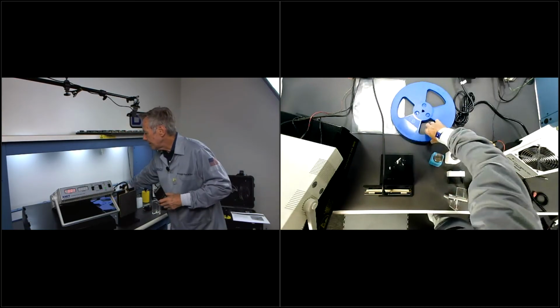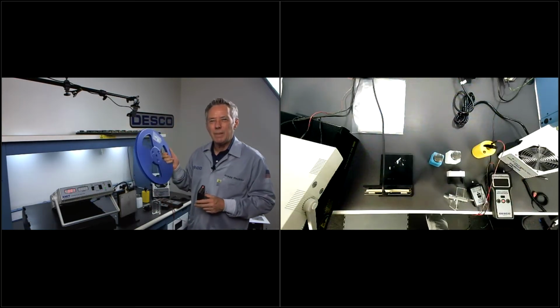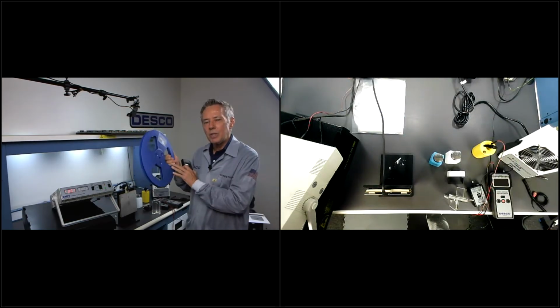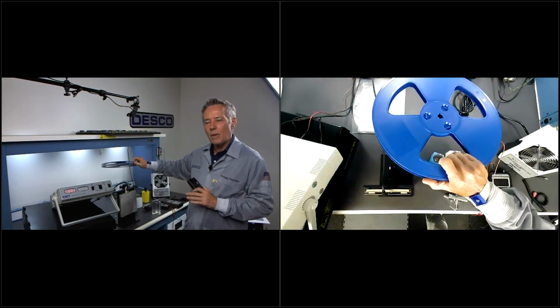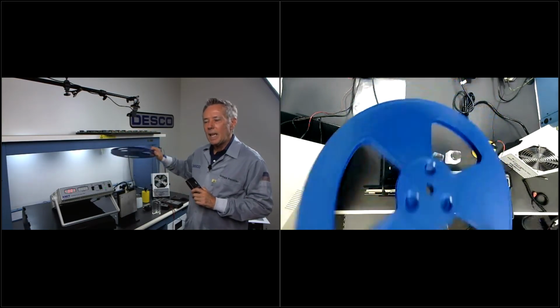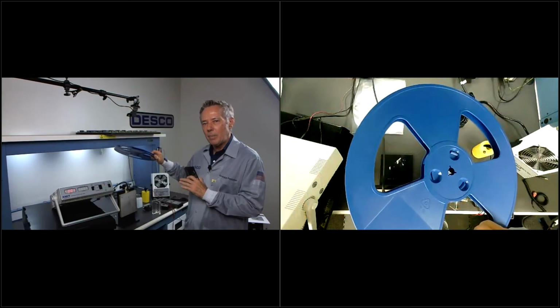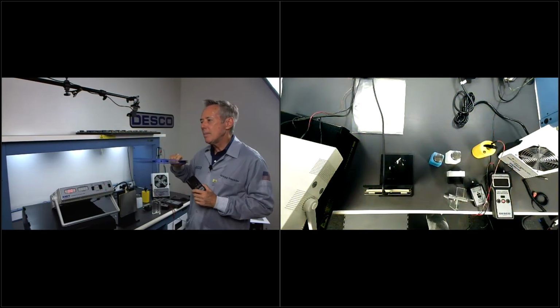Let's say I have this reel in my environment and I want to know if it's okay to use. If this reel would generate more than 2000 volts, I need to keep it more than 12 inches away from my part. If it generates more than 125 volts, I need to keep it more than 1 inch away from my part. That, though, is something I can move.